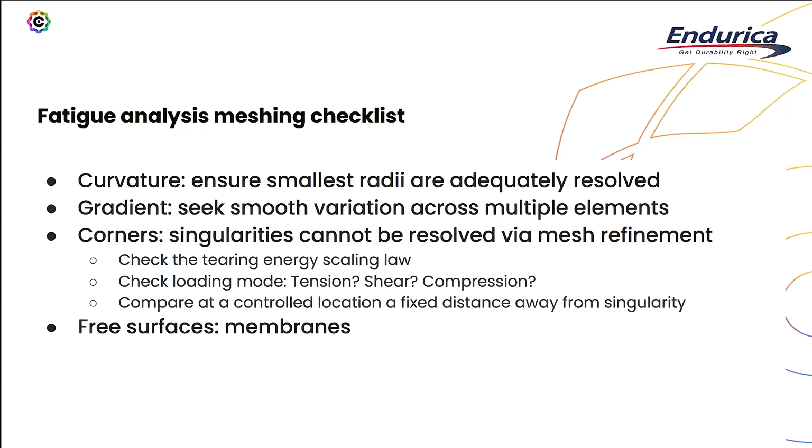The final thing I'll mention is a topic that we didn't really talk about, and I think in future we'll probably follow this up with more information about this. But one of the practices that we use here at Endurica very frequently is to skin our solid element models with a set of membrane elements.